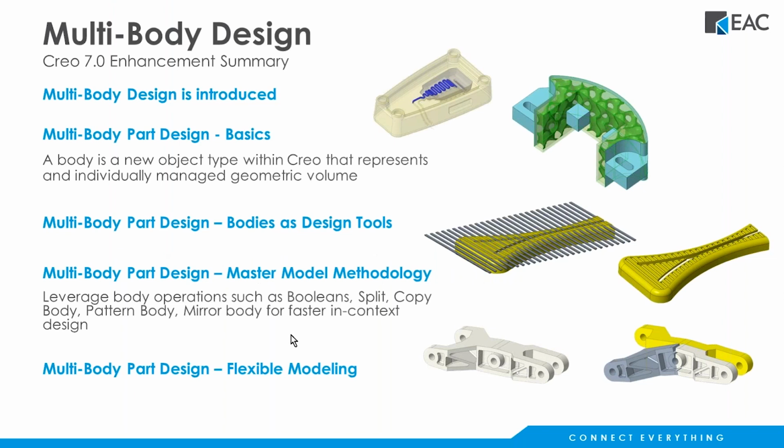We've been able to do multi-body design in a way because we could make separate quilts in the same part, then move them around and subtract one from the other and do that Boolean kind of stuff. And now it makes totally separate bodies, but still in the same .prt file, the same part file. So why would you want to do that? Maybe in this case, here's a mold and we want to run in a cooling line and then subtract that out, using that multi-body concept to create a final body, subtracting one from another.